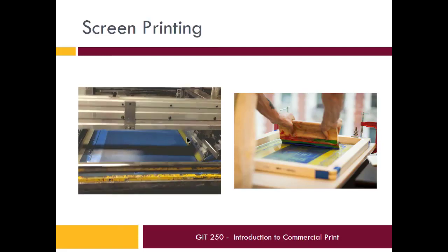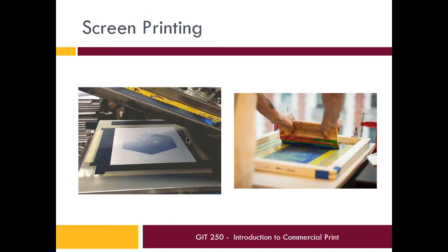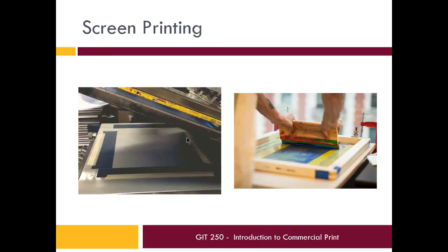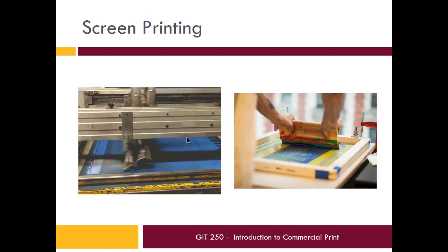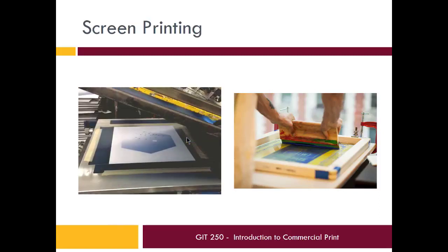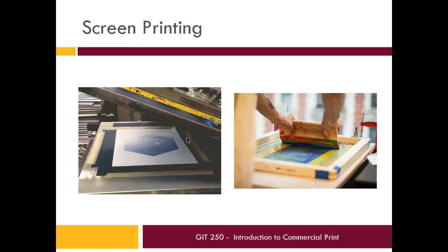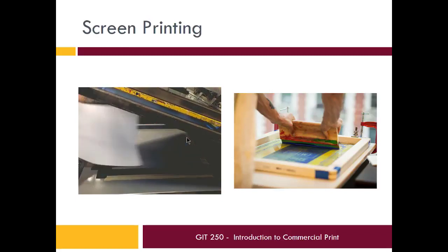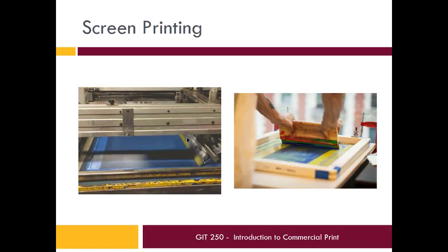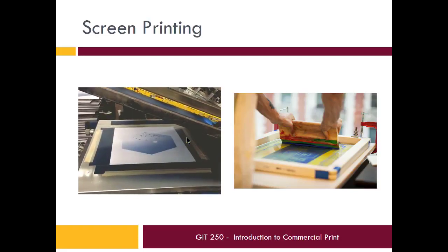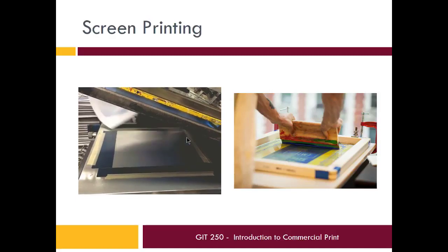Very nice results. Screen printing is very desirable, but again, it's kind of expensive because it's not fast. You have to do a lot of labor on each print, which adds up. On the right-hand side, you can see it being done by hand instead of by machine. There's a frame with a screen, and it's clamped down tightly, and then ink is squeegeed straight through that screen onto your substrate.